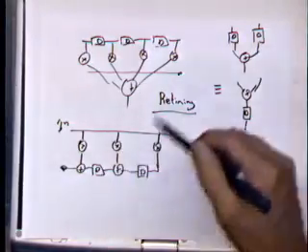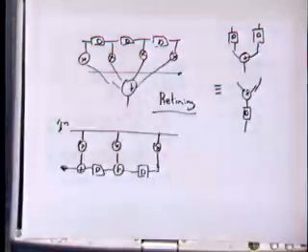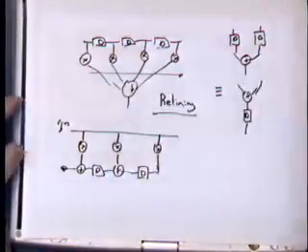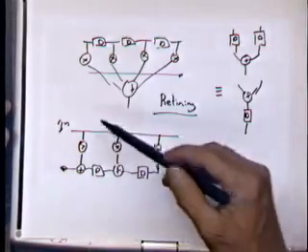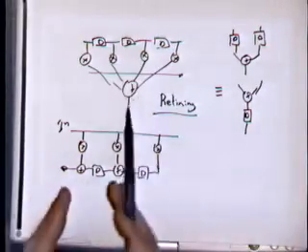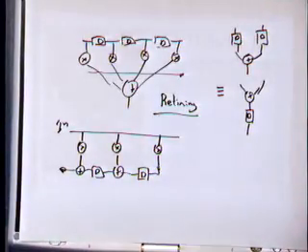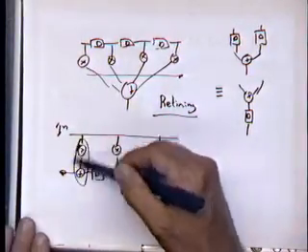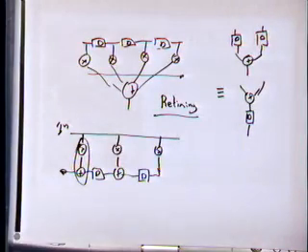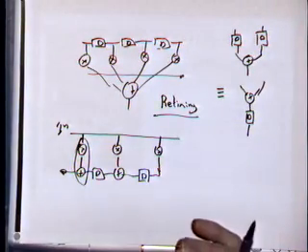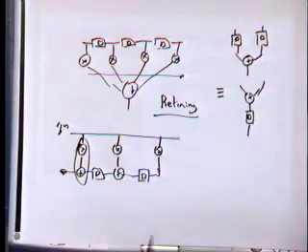So now you can see that where originally, if you had a long FIR, it would have a lot of adders in the chain, which creates a long critical path. Here what I do is move the delays in between the adders. And as a result, I can nicely cut down the critical path, so basically one add and a multiply. Okay? And in some sense, that's what a lot of you did, maybe not realizing that this is something that can be structured and automated, but that's a lot of what you did.